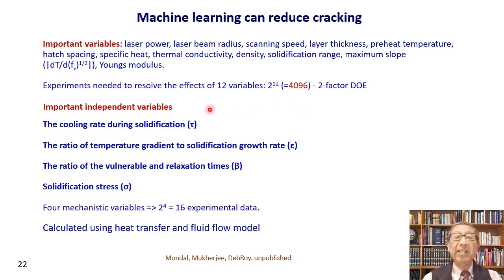So if we look at the peer-reviewed literature, we find that the cooling rate during solidification is often mentioned because it determines the scale of the microstructure, and the ratio of the temperature gradient to solidification growth rate determines the morphology, which is often tied to cracking.